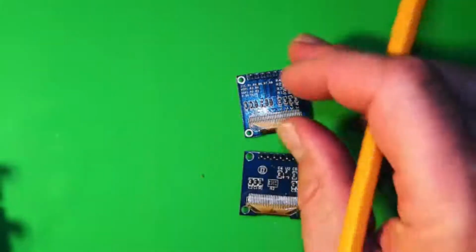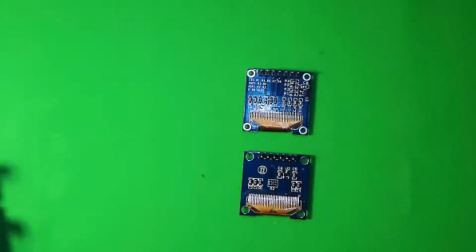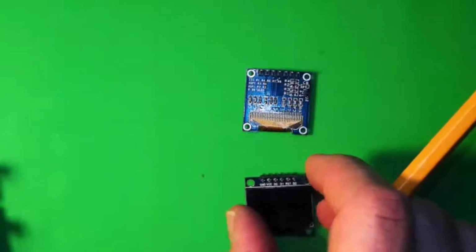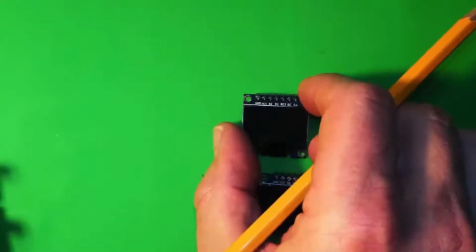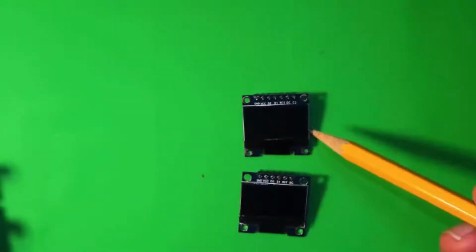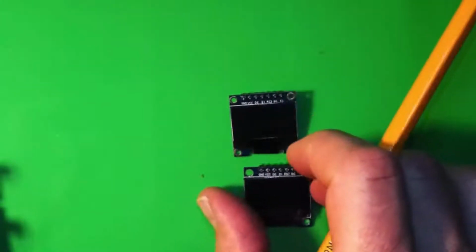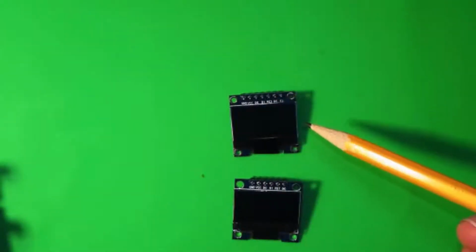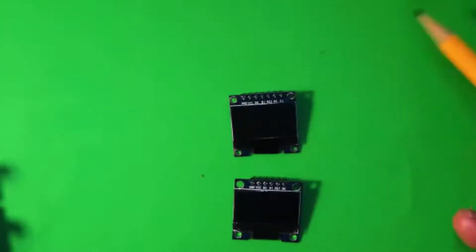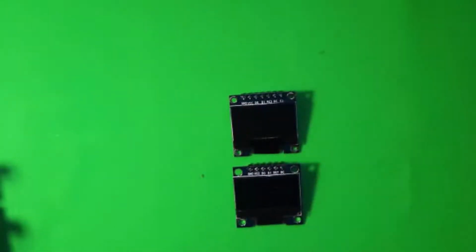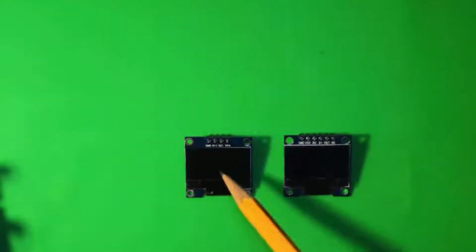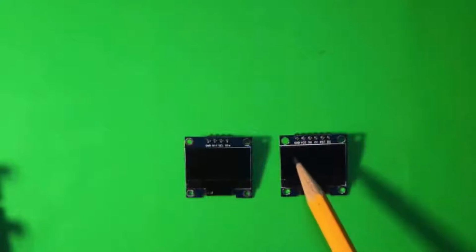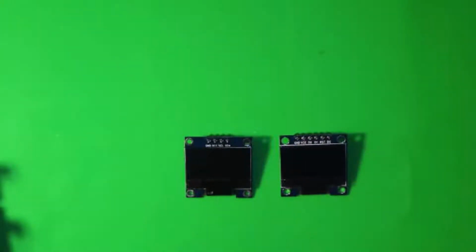You can see that they look a little different, okay, on the back side. So beware when you're buying them to know what you're getting. In most cases, the ones with the chip select may cost a little bit more, but it's important if you're kind of short on digital pins to get that, so you can, for example, share lines on this with your SD card. If you don't need to worry about that, then you can get this one, which is lower cost. Today's example, we're going to use these two, the I2C version and the 6-pin SPI version.